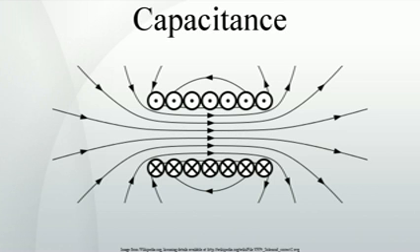Frequency-dependent capacitors. If a capacitor is driven with a time-varying voltage that changes rapidly enough, then the polarization of the dielectric cannot follow the signal. As an example of the origin of this mechanism, the internal microscopic dipoles contributing to the dielectric constant cannot move instantly, and so as frequency of an applied alternating voltage increases, the dipole response is limited and the dielectric constant diminishes. A changing dielectric constant with frequency is referred to as dielectric dispersion, and is governed by dielectric relaxation processes,